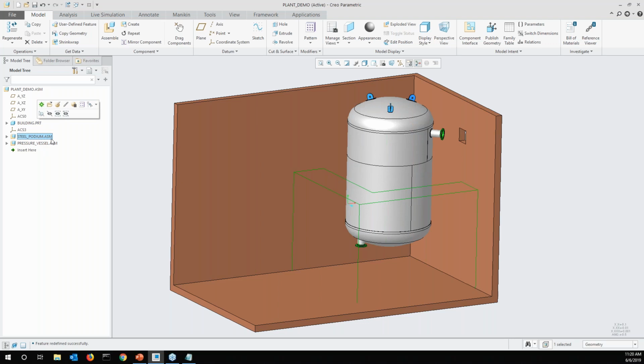assembly. And if we simply expand this assembly, as you can see, there are no skeleton features on this. So I built out these sketches within the assembly environment. There are no parts here within the assembly environment. And so I'm just going to use this to capture where the beams are going to be placed. So this makes it a lot easier.